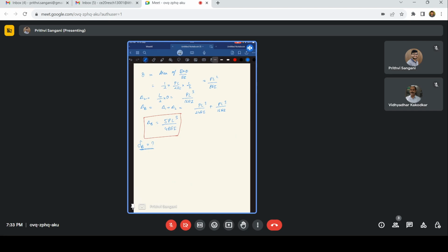How do we solve for this? Let us first discuss the static indeterminacy. Let me draw the beam again, something like this. We can have bending moment M here. We can have vertical force VA, and also horizontal force HA. We can have only a vertical force VB. Sorry, this is VC.